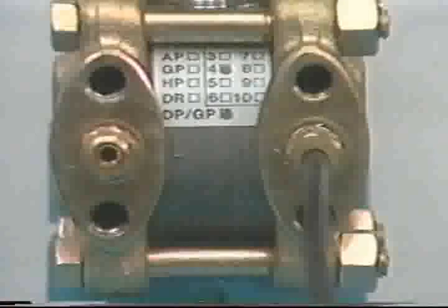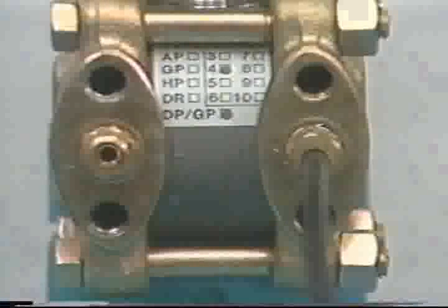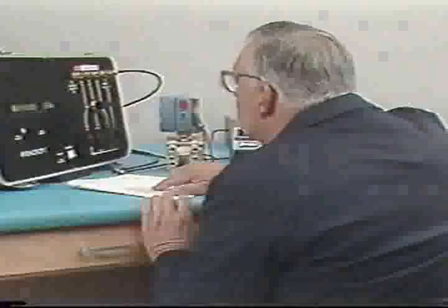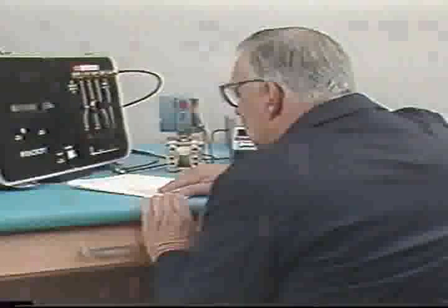The transmitter is connected to the low-pressure calibrator. Remember, the source of pressure is connected to the high-pressure port only. The low-pressure port should be vented to atmosphere. Once the equipment is connected, you'll need to determine the instrument's range and the appropriate test points for calibration. To do this, you'll need to know the minimum and maximum pressures the transmitter will be subject to.